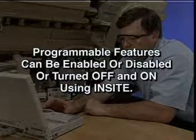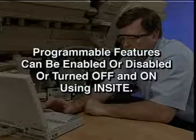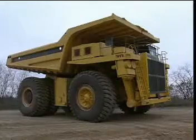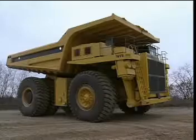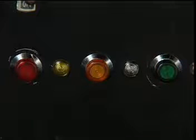Programmable features are those items that can be enabled or disabled or turned off and on using Insight. Quantum engines can be calibrated with an optional engine protection feature that monitors critical engine temperatures, fluid levels, and pressures. The engine protection feature records separate fault codes when an out-of-range condition is found for any of the engine protection sensors. The engine protection feature will then light the engine protection lamp.